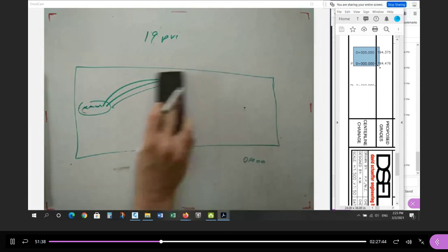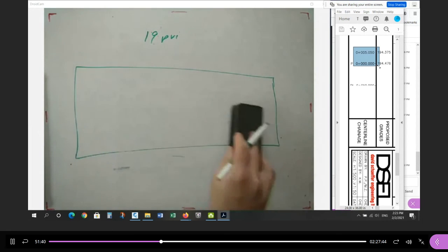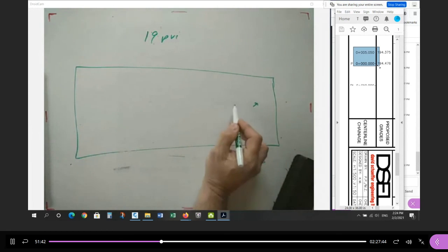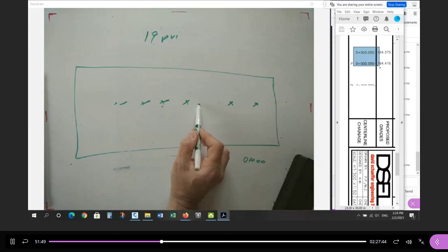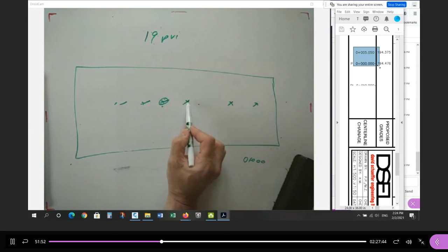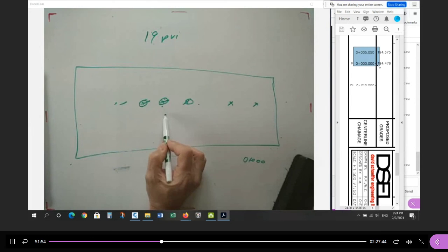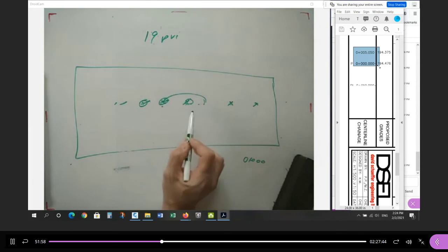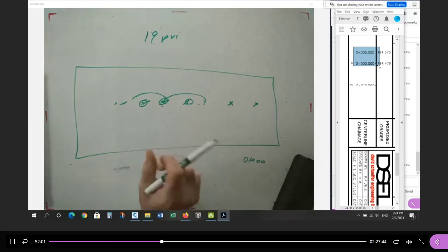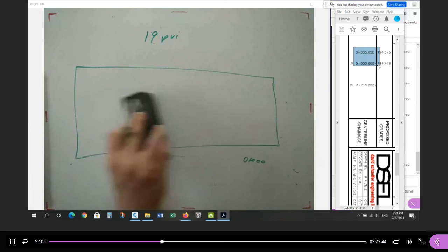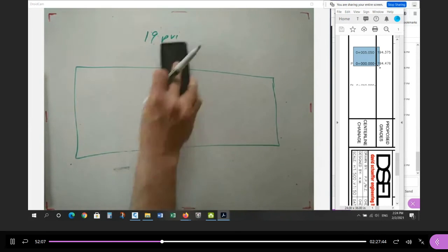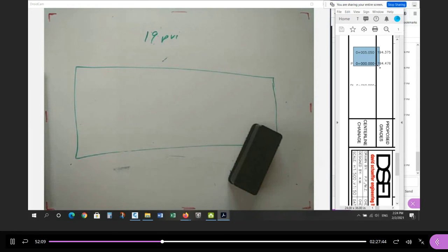Because again, if I guess, here's the danger, it's going to get upset. And I'll demonstrate this to you. If I try and guess where 0 is and where 5 is and where the next one is, and so on, if the fourth station wants to be less than the third, it won't let me type in a number less than this or greater than this. So if these are correct, but then the fourth one is here, but it should be here, it won't let me jump position. They have to stay relative to each other. So by practice, I put them all at the end, and then I don't have to worry about that. Okay, let me show you. 19. So here's what I do.